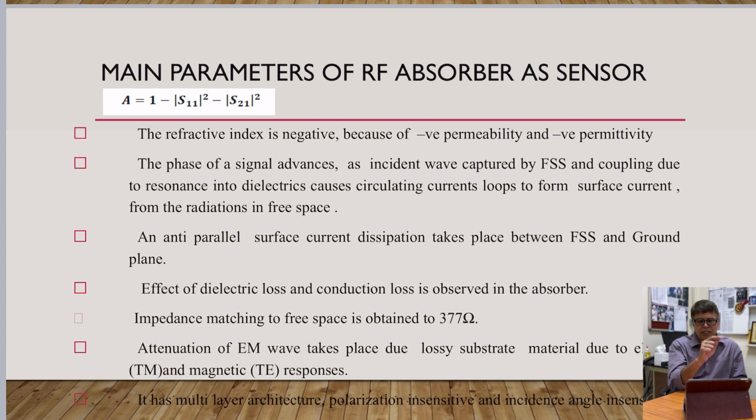So SRR or ERR is nothing but a combination of inductance and capacitance. Now, if these inductance and capacitance are connected in series, we already know there will be a particular resonant frequency, and the frequency formulation will be f equal to 1 upon 2 pi root LC. So L and C are responsible for a particular operating frequency. The design frequency of SRR depends on the frequency we are designing for, so the length of the inductance and the gap of the capacitance will constitute the frequency parameter.